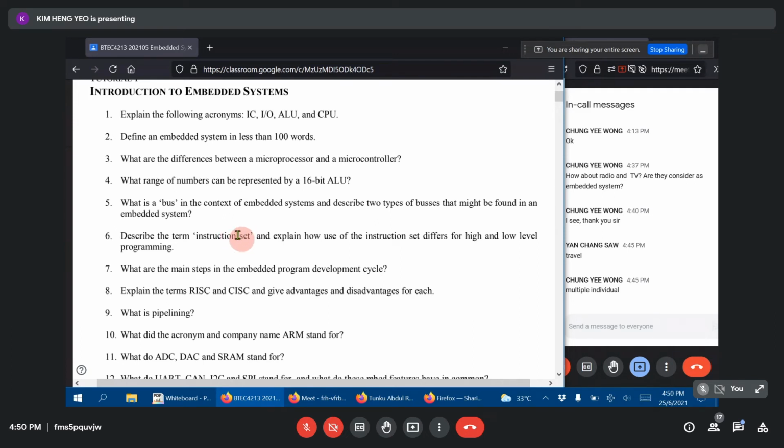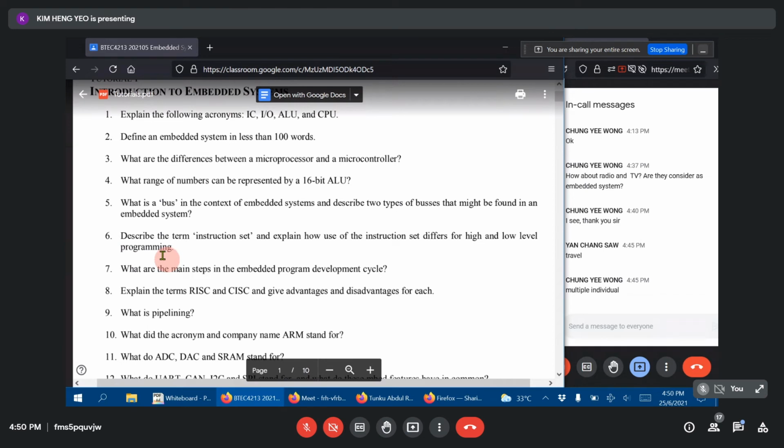So in order to access those special operations, what are they? For example, put the processor to sleep. If you want your processor to power down, put it to sleep, you have to execute some special assembly instructions. And there is no equivalent in high-level programming. You cannot access it, so you have to program in assembly. This is one of the main reasons for using assembly.